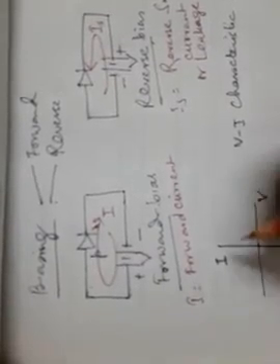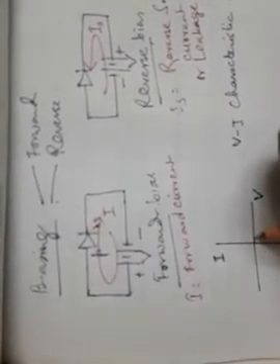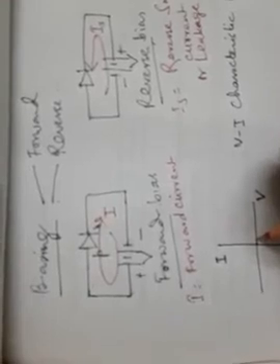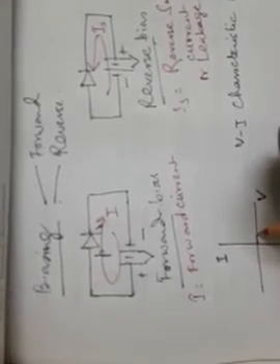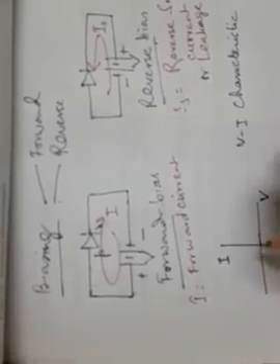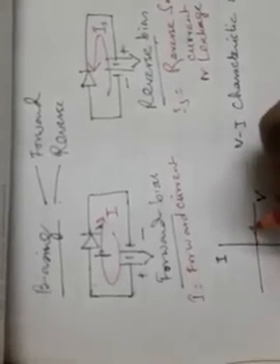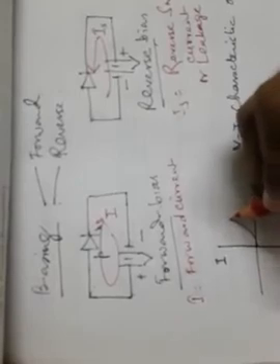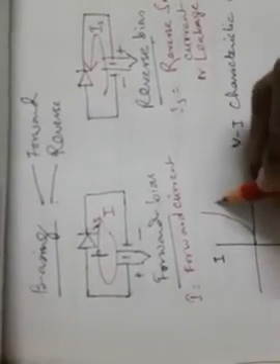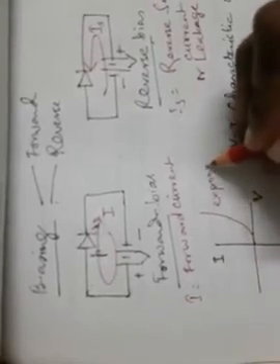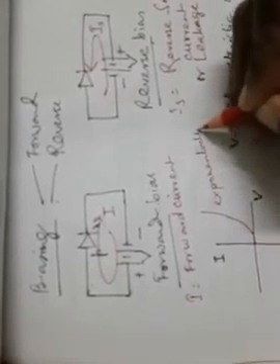During the forward direction, after a certain voltage, the conduction by the diode is still negligible, but when that certain voltage is crossed in the forward direction, the current through the diode increases rapidly. Rather, it is said to rise exponentially.